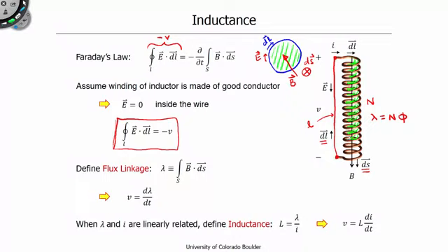It is similar to if you took a coil like this and dipped it in soap water and then pulled it out, you would see that the soap film actually forms that surface S. And if you visualize the magnetic field cutting through that, you can easily see that it is cutting through this surface n times if there are n turns. Hence, in this case, the flux linkage is really n times phi.